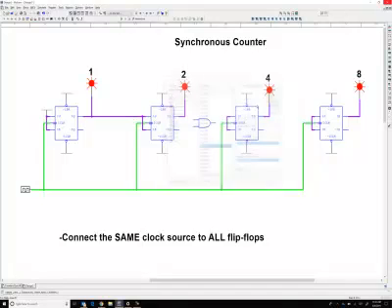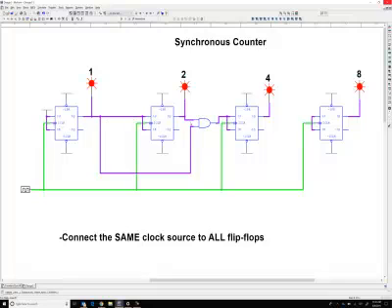It doesn't matter where you put it. Some people build these counters vertically. It's up to your layout preferences. So what I'm going to do is this AND gate is going to give a 1 to JK, making it ready to toggle when the 2's place is a 1 as well as when the ones place is a 1. So what we're going to see is when the ones place is on, the twos toggles now, and then when both of them are on, the fours place toggles now.